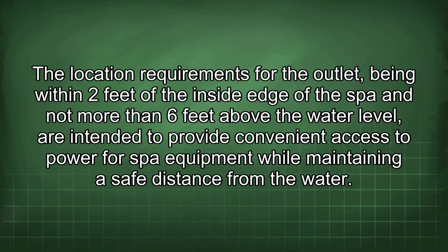The location requirements for the outlet, being within 2 feet of the inside edge of the spa and not more than 6 feet above the water level, are intended to provide convenient access to power for spa equipment while maintaining a safe distance from the water.